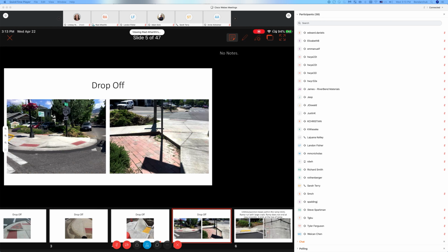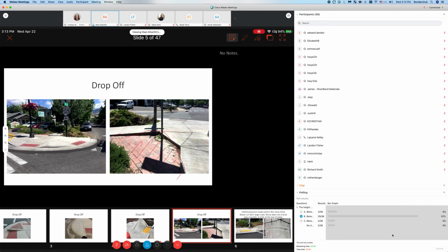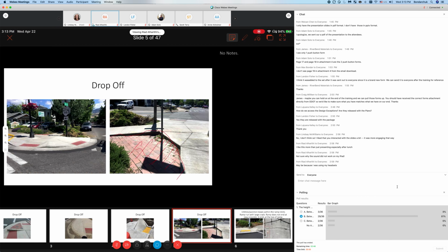Another drop-off. Obviously, this is not a contractor issue. As it has been constructed, we find here this brick in the back of the ramp, creating this drop-off. And the solution here could be to go back and, if the ramp otherwise meets conditions, just remove the brick and bring that level so there would be no drop-off. And because it's a non-traversable surface, it would be good to have that landscape, softscape.